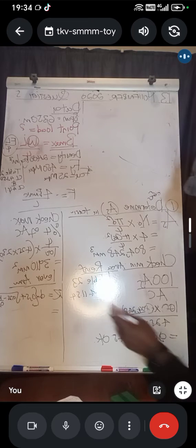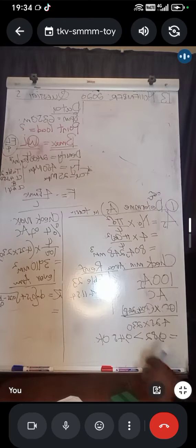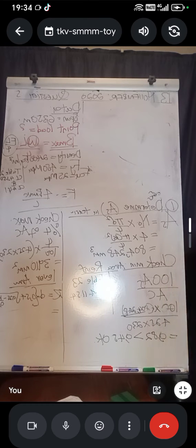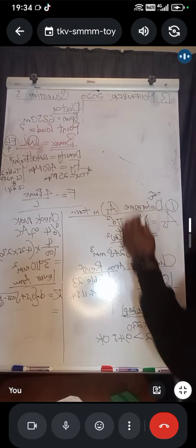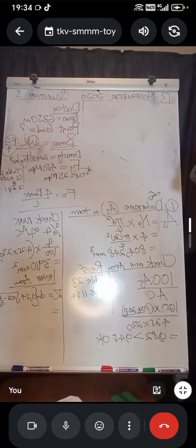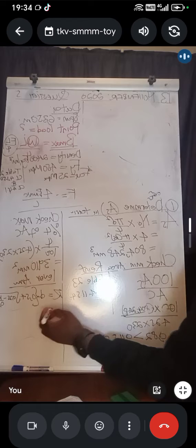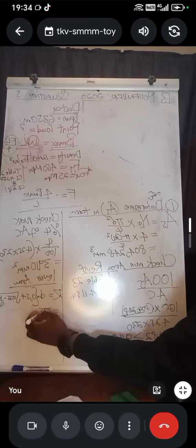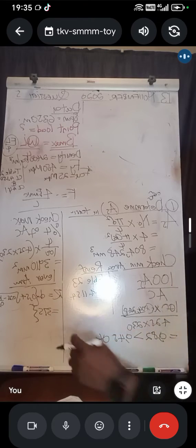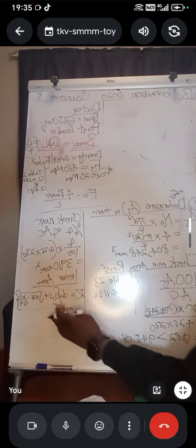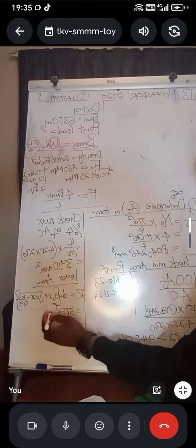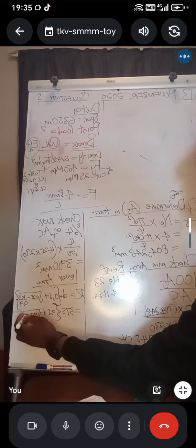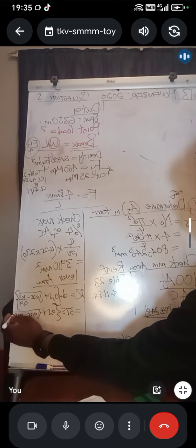When we substitute there, what is the effective depth here? Because this small d is the effective depth. I erased it, but it is 375. So it's going to be z equals 375 times 0.5 plus the square root of 0.25 minus 0.156 divided by 0.9.